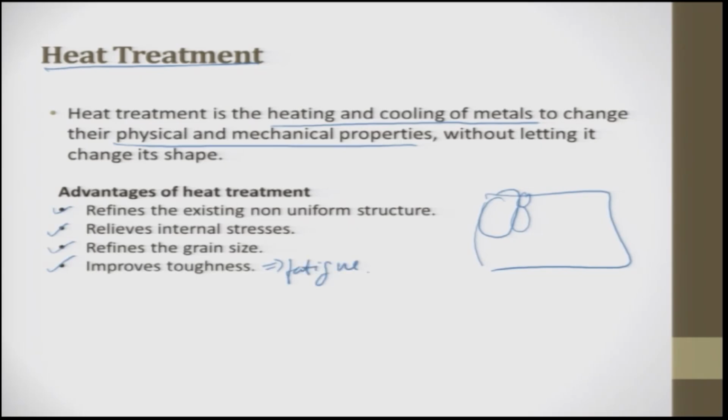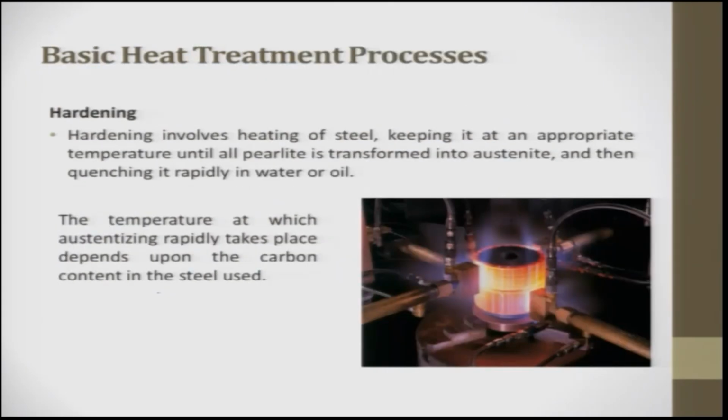Fatigue behavior you want to enhance. So, that is what we do. If you make the grain size smaller, then the workpiece is going to demonstrate high hardness. If the grains are large, then the toughness is going to be large. So, this affects the mechanical and physical properties of the material.